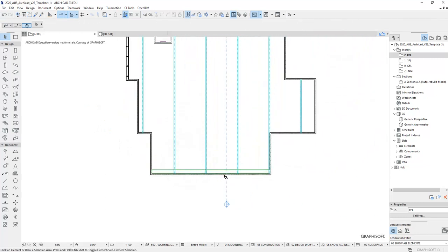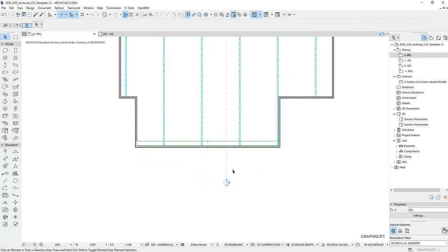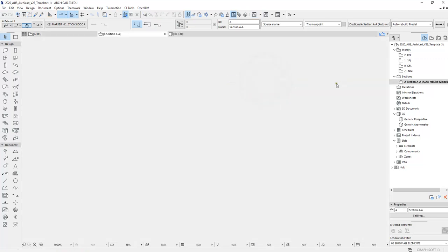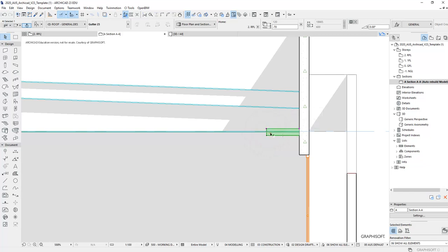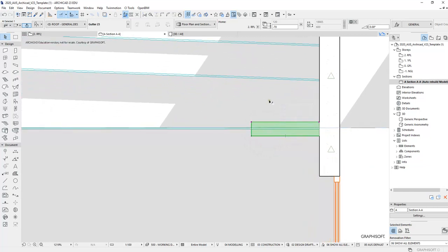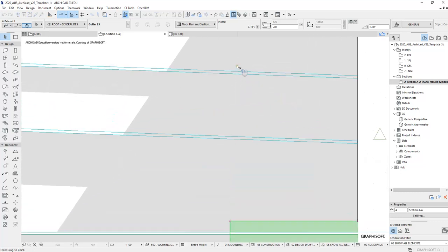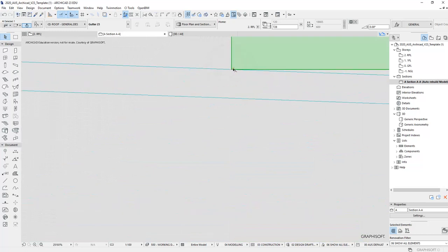Okay. Now, what is the height that my gutter is currently sitting at? I'm not sure, and I can say, oh, I forgot to check. That's fine. So what I'm going to do next is simply jump straight into my section view. And as you can see, this is where my gutter is sitting at. And it's not great because it's cutting into my ceiling. So I'm just going to elevate the gutter by pressing Ctrl D, which is move. And then I'm just going to click on this corner, hold Shift, move it up, and perhaps I'll just snap it to the top of the universal beam.